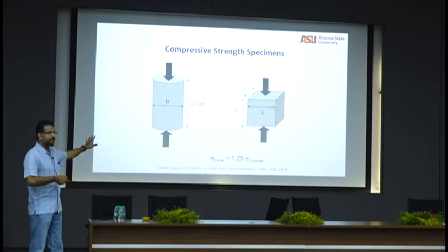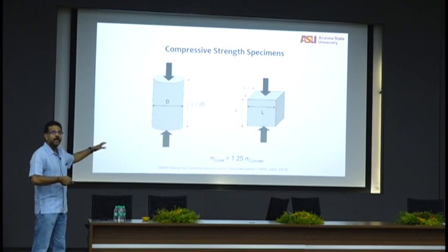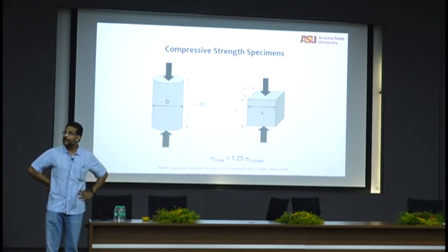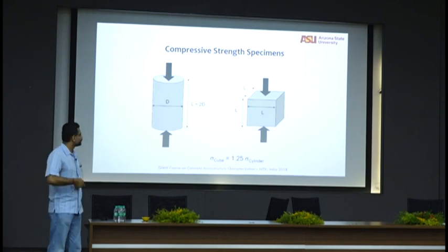Get the idea of what happens when you do strength testing? So when you do strength testing of cubes, always know that your M40 concrete in another part of the world will only be an M35 concrete or M30 concrete, depending on how you test it. Okay.